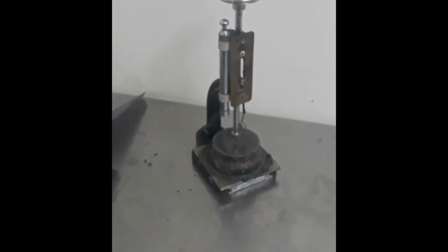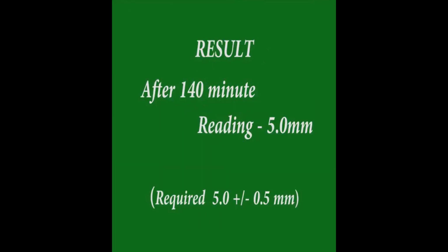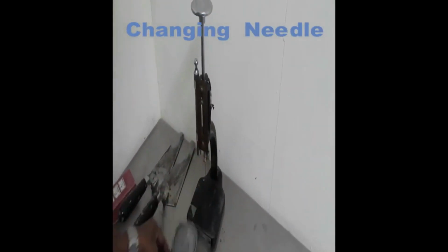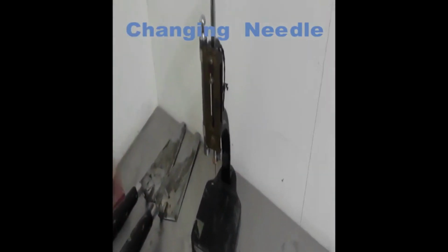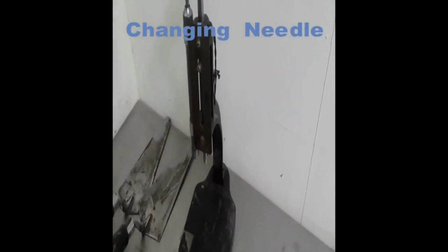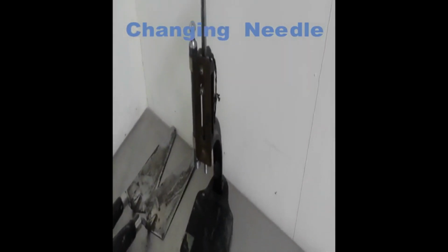This is done at numerous periods after the initial setting time. We keep on repeating this until we reach a time when the paste has become so hard that it is unable to penetrate more than 0.5 mm. So from this video, it's clear that the final setting time is the time from when the water is added to the cement to the time the paste becomes so hard that the needle does not penetrate more than 0.5 mm.